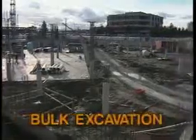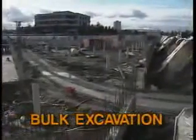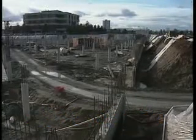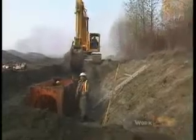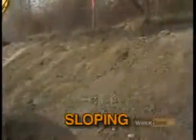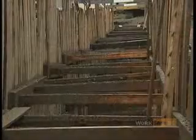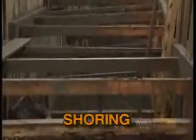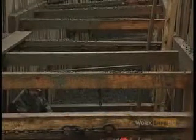A bulk excavation refers to excavations wider than 12 feet, such as basement excavations. Sloping is a system where the sides of an excavation are flared to a safe angle. Shoring is a support system designed to keep the sides of an excavation from caving in.